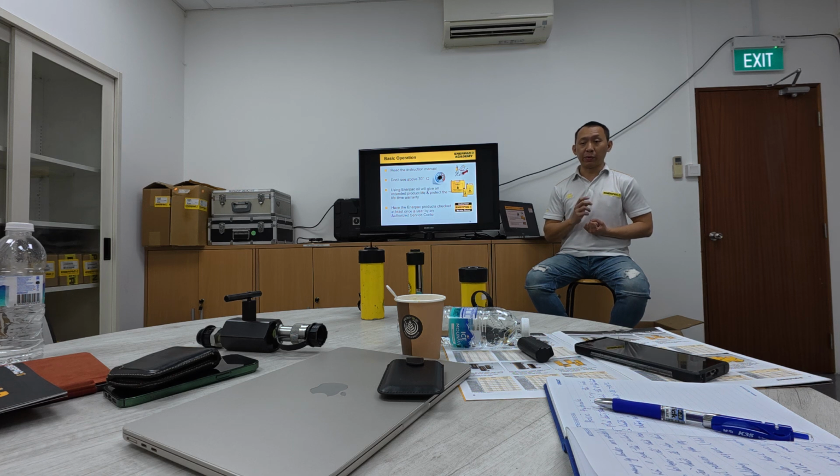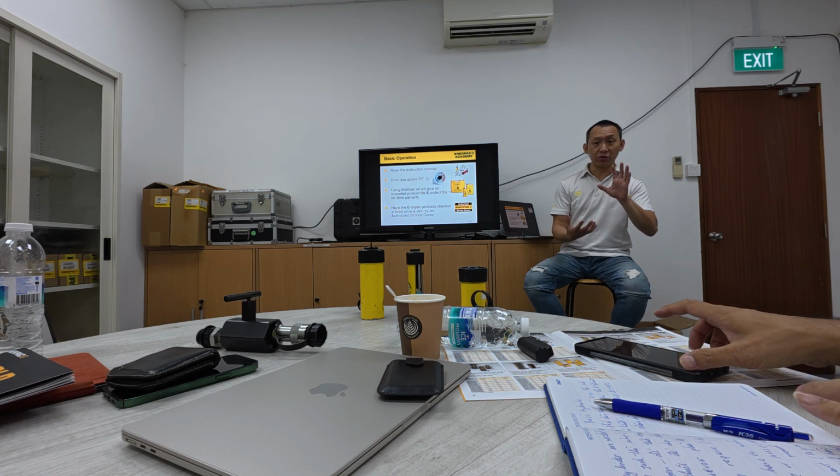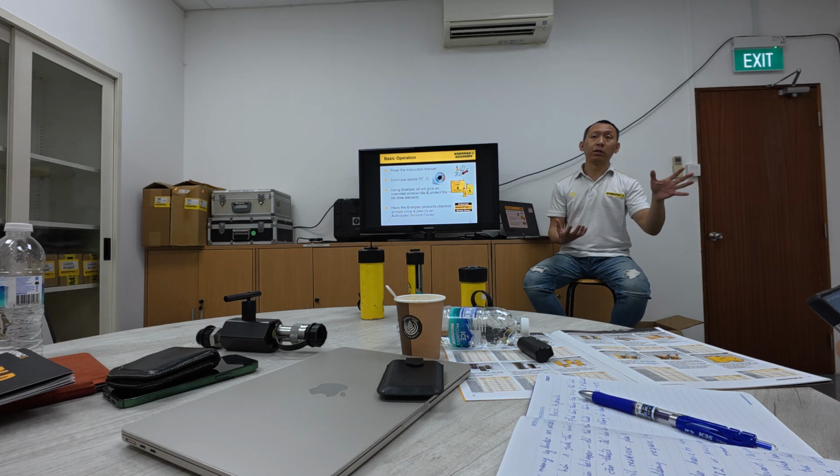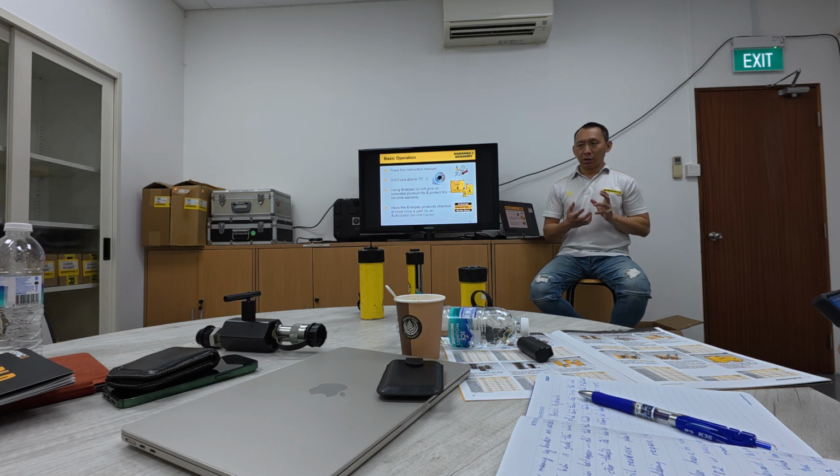Based on their evaluation, maybe I see a cylinder that is leaking. You can extend the rod, but it leaks. Most likely it's the seal inside, and you have to replace it. So you can tell the customer, we checked, it's leaking, so probably you need to change the seal kit, and we have to charge you for the seal kit and the labor. If the customer says it's so expensive, I won't repair, then okay. But if the customer says, I think I want to repair,